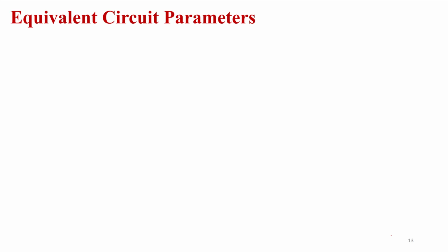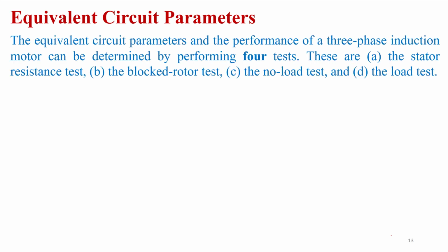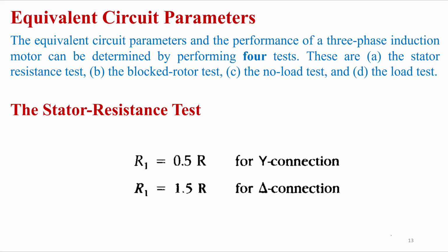Multimeters, yes, very good. So we now see the tests which we generally conduct on an induction motor to find out the parameters. One is your resistance test, the stator resistance test, then Blocked-Rotor test, no load test, and load test. Load test is just to find out the efficiency. So the stator resistance test is this. We connect across two terminals.